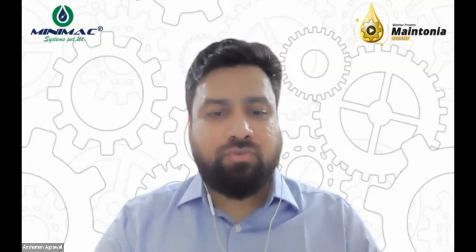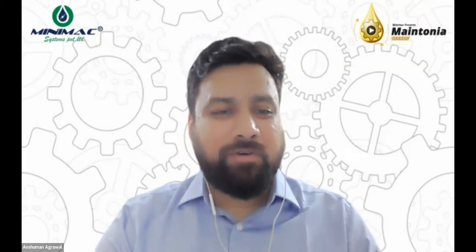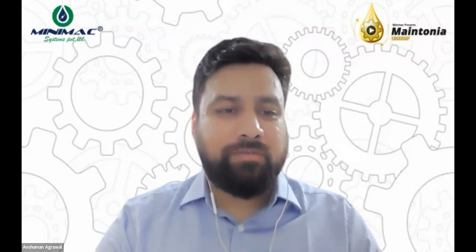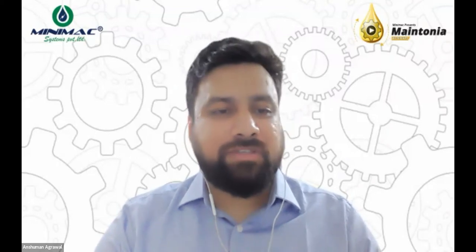Right. So again, it is of hygroscopic nature. Yeah, of course. And as it's of hygroscopic nature, which is a stronger hygroscopicness as compared to the FRF or phosphate ester fluid, probably the moisture which is on the surface of phosphate ester fluid would again be picked up by the nitrogen which is passing through. Yeah, rightly said. Okay.